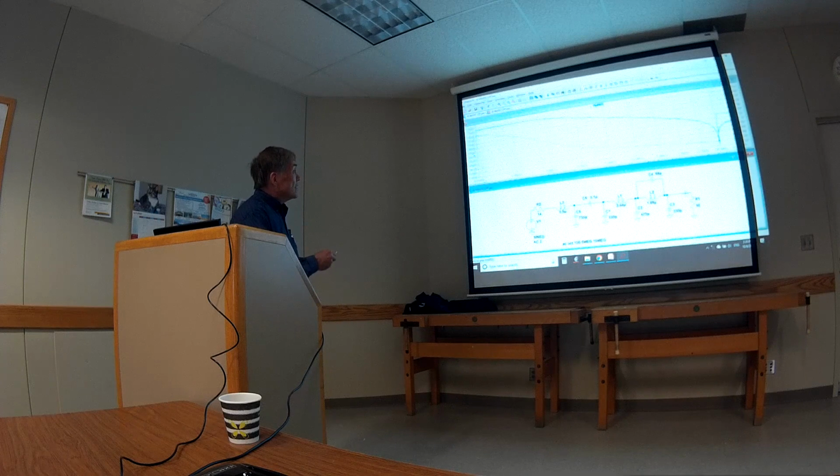Now, you see at 7 megahertz, it's just right there, it's full until 7 megahertz plus. And by the time you get to 14, we don't even count the bottom, say it's a little bit off 14, you're still down to 80 dB. I mean, that's really suppressing that second harmonic. It's really a nice filter.